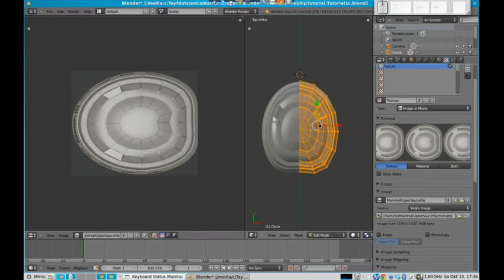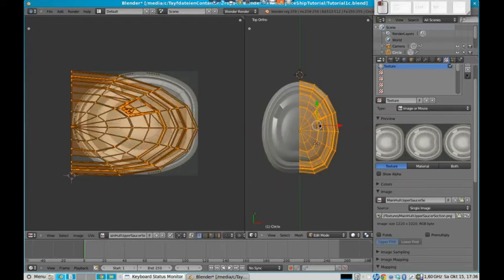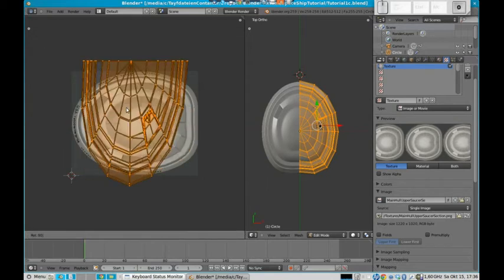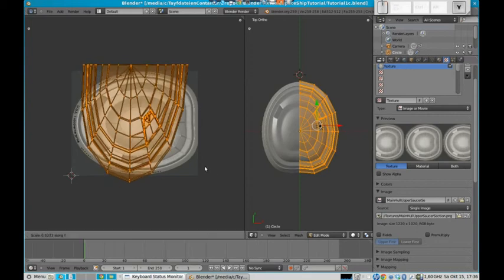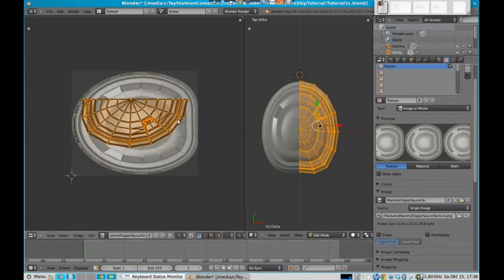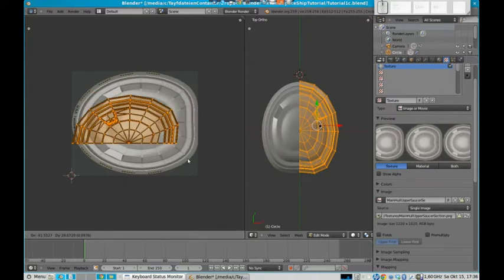Considering my experience, the easiest way of doing textures is just to divide your mesh into different parts which can be seen from one view like this. This view from above is quite flat, so we can just go to this upper view and say project from view. So we will have exactly the same shape here, but since the image is rotated and Blender does not know that, we either have to rotate this one too, which can be done exactly like we did all the time, and then scale it according to the y-axis. It's the wrong direction, I see, so I will rotate it by 180 degrees and put it there and so on.